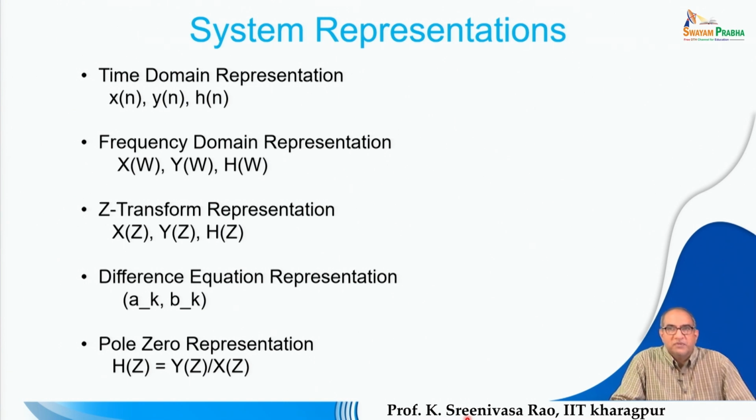spectrum for the given speech segment. For that we observed the various Fourier transform relations in continuous time, discrete time, and the discrete Fourier transform relations. For performing the discrete Fourier transform, we observed what the actual true signal and its corresponding natural spectrum are, and the moment you want to use the discrete Fourier transform, what the various trade-offs and approximations are, or the operations that are performed on a signal in various steps. For each operation, what will be the loss of information, and all those aspects we discussed graphically.